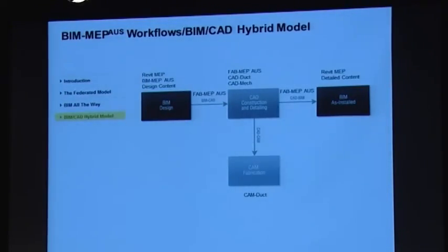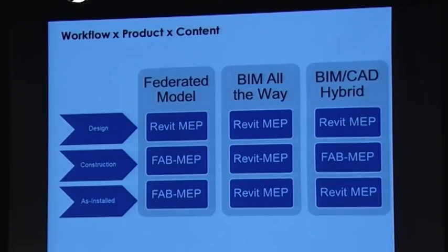And then the round tripping, the hybrid of this, is basically starting off with the Revit MEP content, pulling that through Fab, doing your workflow in CAD-DUCT and CAD-Mep, and then writing that back through the data content set within the data content environment, back into Revit as a native component in Revit, and then dropping out for your fabrication. Okay? This is just another way to look at what's required data content-wise.